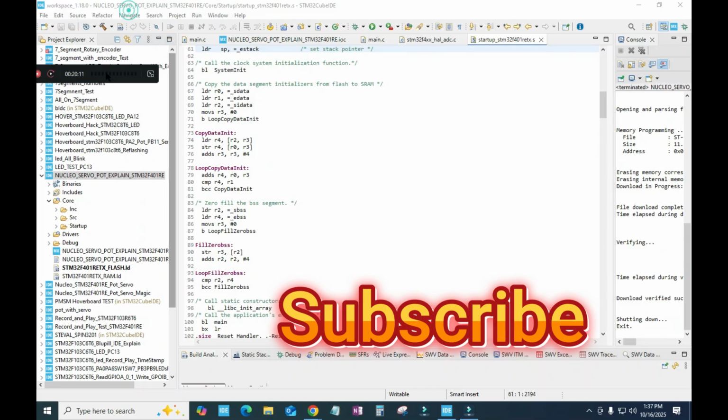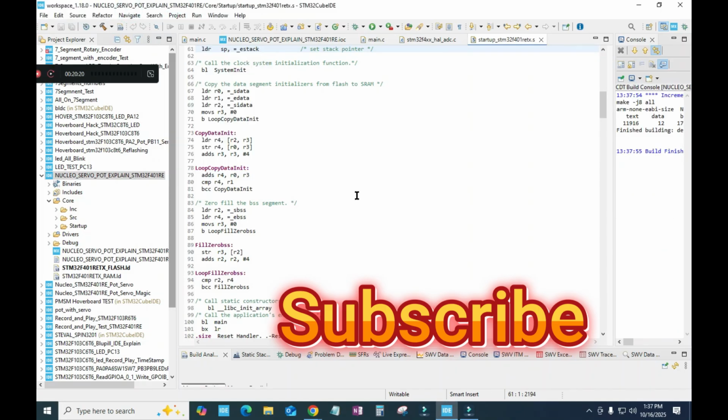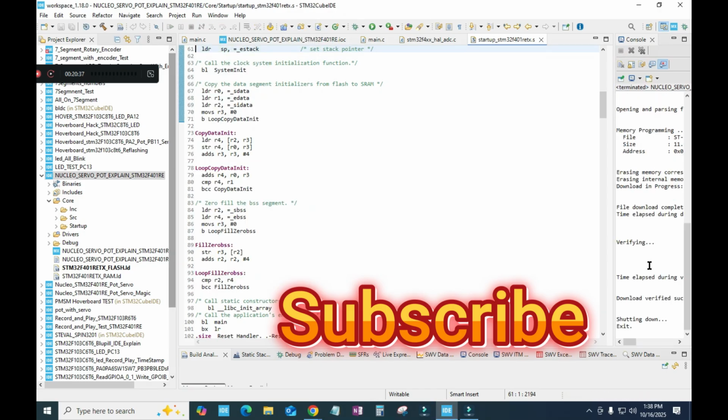and finally go here to the project. Flash that, connect the USB port, go to Run, Debug, and your servo is moved to 0 and after that, whenever